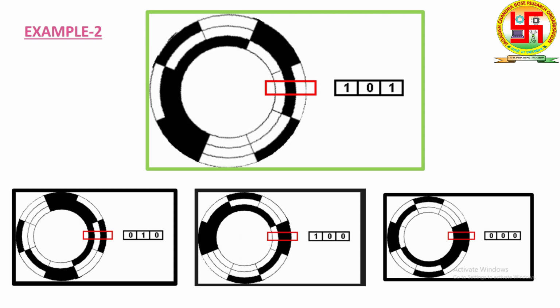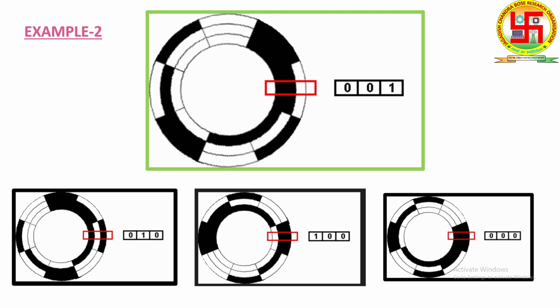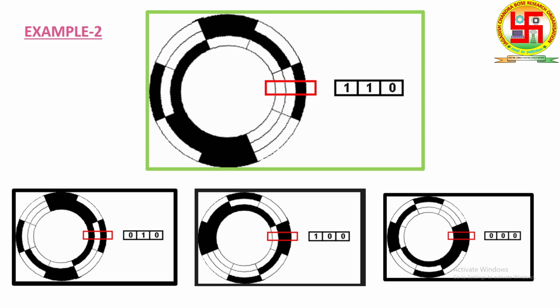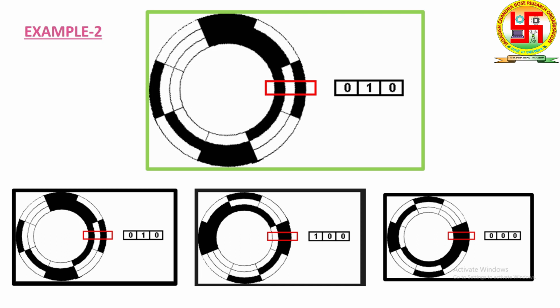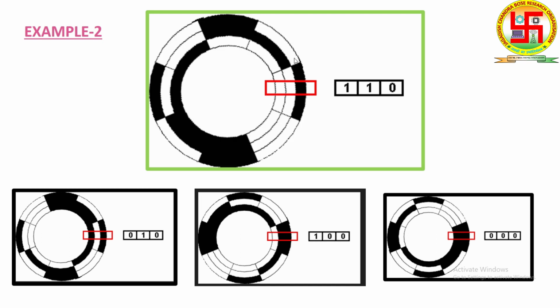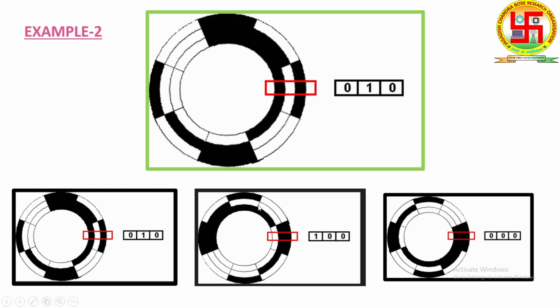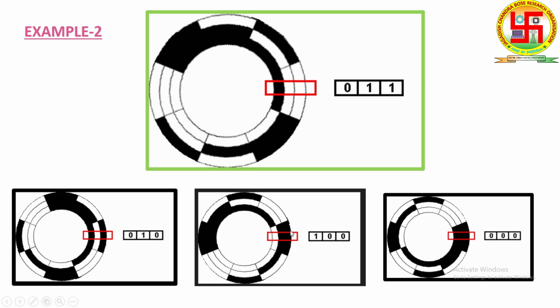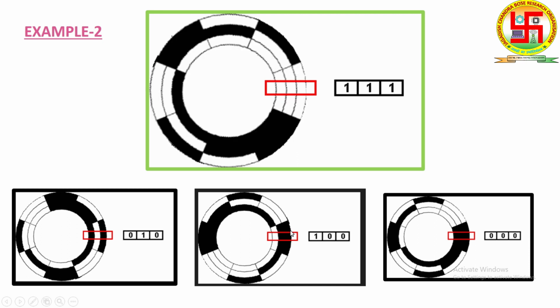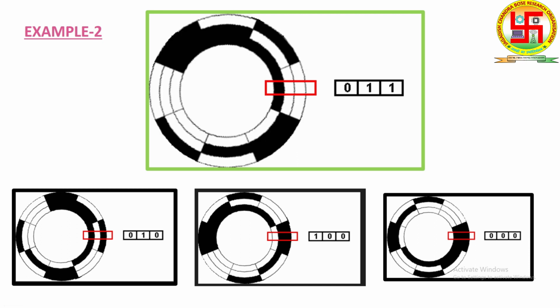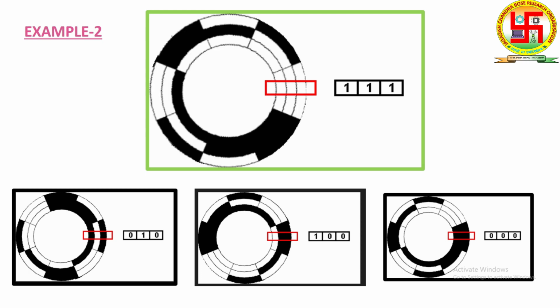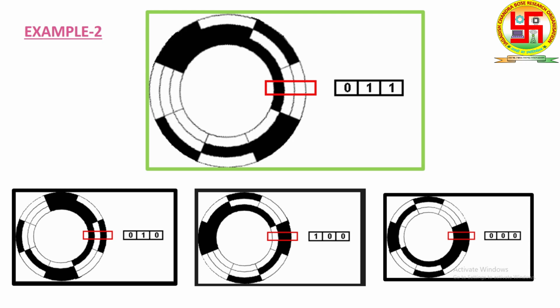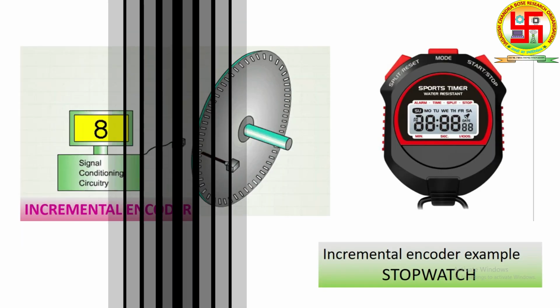So one segment corresponds to 45 degrees. This 45 degrees comes after dividing 360 degrees by 8. That means this one block where the code is not changing is for 45 degrees of rotation. So by this we can find how much absolute degree this wheel has been rotated.